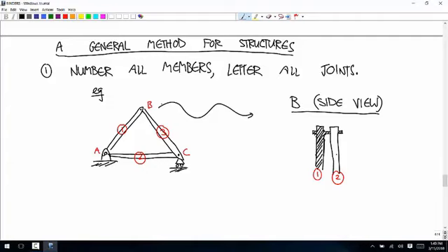Yep. When you mentioned that if it was a pin joint down at C, it'd be over constrained. If we have pins that are over constrained, does that basically mean extra pieces? Yeah, that's a good way to think of it. Not necessarily a whole member, but it means that you can put in a wimpier joint, a joint with fewer restrictions on it, or a member, and it'll still be at rest. So if this was a pin joint, we would be able to remove one degree of restriction from that pin joint, make it into a roller, and it would still stay static. And so that means that we can't calculate it there.